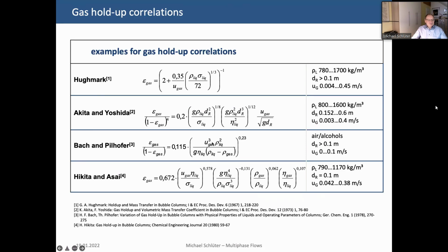Of course, we have the superficial gas velocity, and maybe this is directly related to the energy dissipation rate and turbulence, but you will probably agree with me that this very strongly depends on the size of the reactor, if this really creates turbulence or not. And it depends on viscosity and the homogeneous distribution of the gaseous phase and very, very many other parameters.